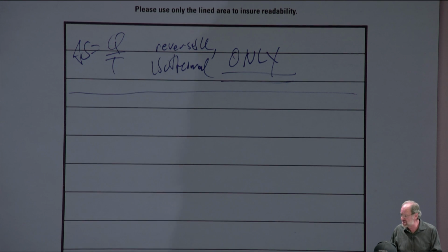The isentropic efficiency is the relationship between the actual amount of work or power that is done or required by that device to the ideal amount of work or power that would be required by that device if it were indeed an ideal device. And in this context, ideal means isentropic, right? No change in entropy. And that's why we call it the isentropic efficiency. We're calculating the relationship between the work for the real process, the actual process, compared to the work for the isentropic process, that is the ideal process.